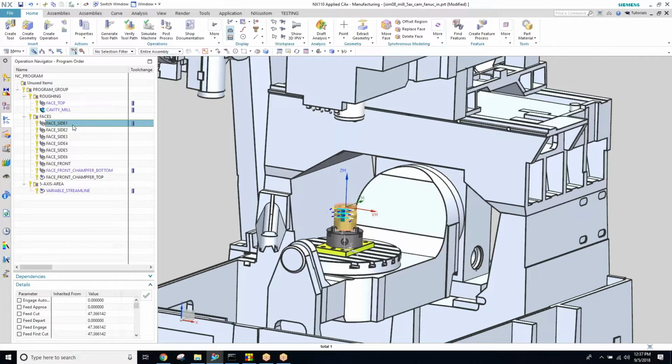And with the way this post-processor and simulation are built, and this is pretty common to all 5-axis machines that we develop, we deliver them together because the post-processor can look at the simulation kit and use that for a lot of the calculations for rotary movement. So it's an advantage on the post-development side. So our normal practice is to always deliver a simulation kit with 5-axis posts for that reason.